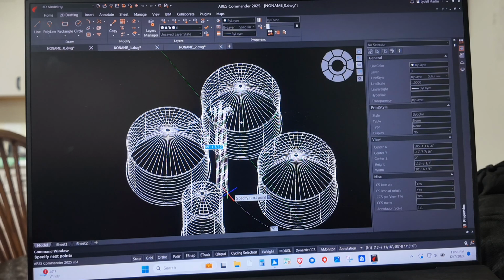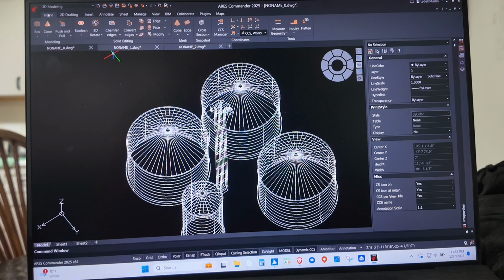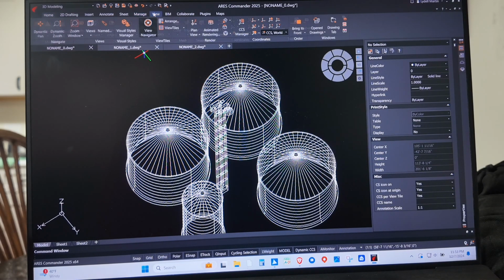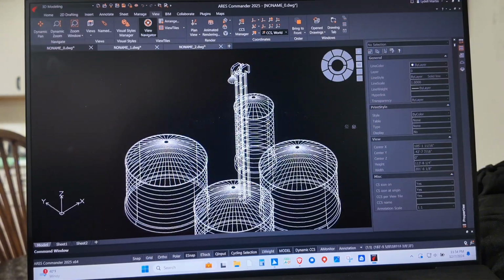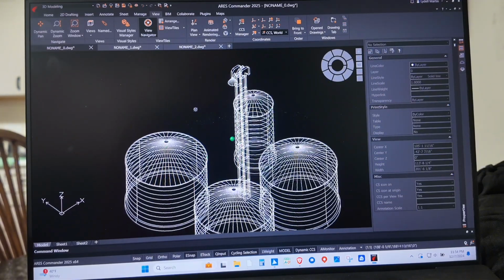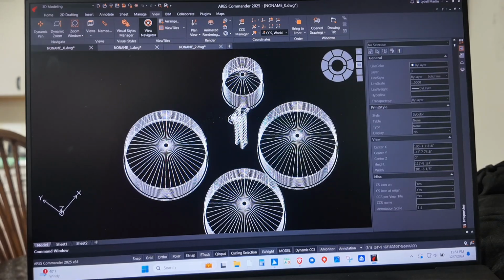And it says 104 foot. Yeah, so that's with the boot, we're 104 foot. That's going to be good. That'll hit everything fine. We won't run into any crazy problems that way. It's better to have your elevator a couple foot taller than to have your elevator not tall enough.